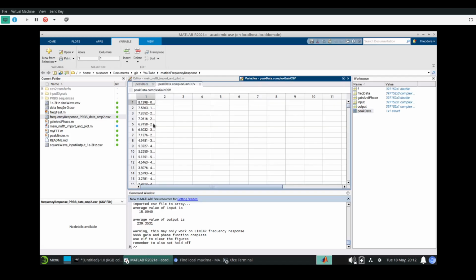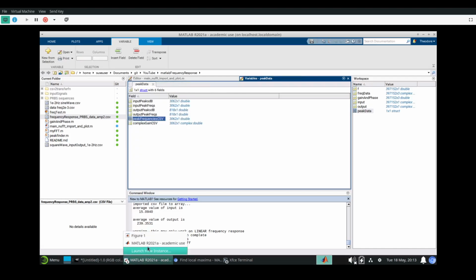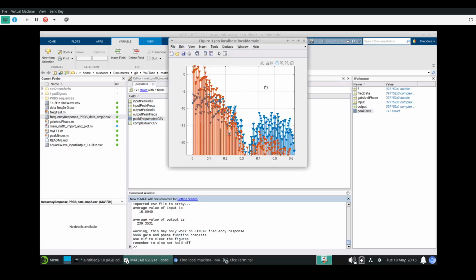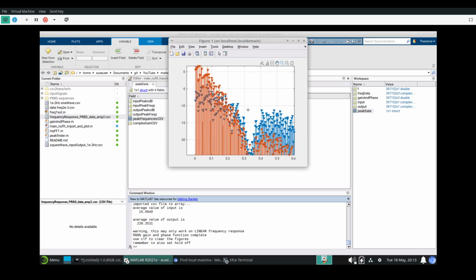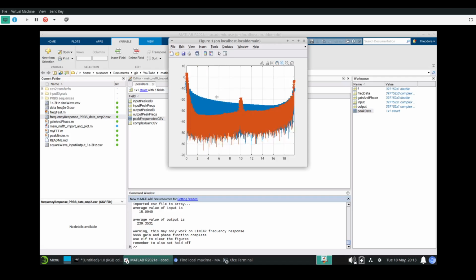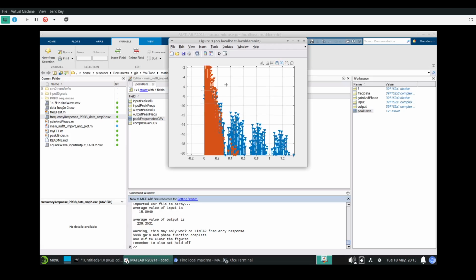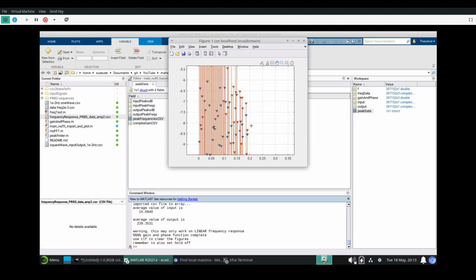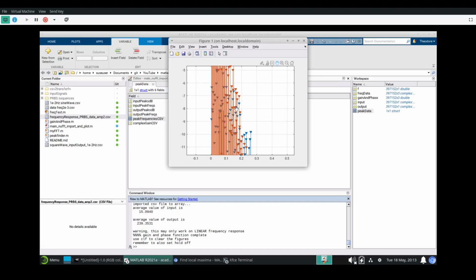And where do you take note of this data? You take note of it at the peak frequencies, that is to say you want to capture this data only at your relevant input frequencies. So what are the relevant input frequencies? It's a little bit hard to see from the decibel based graph because there are so many peaks. One clue: what's in multi-frequency input data? Of course, for one frequency you only look for one input peak, and it's very easy to find where your data should be.